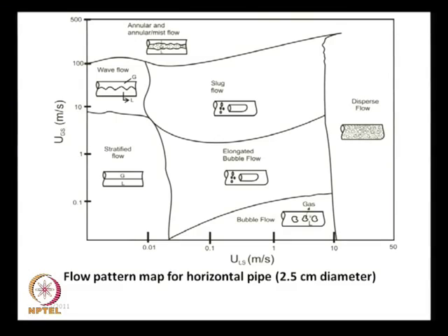For gas solid cases, we find that the Reynolds number and the Archimedes number, I believe you know about these numbers, are much more important. Usually, the maps for gas solid cases are in terms of CD versus Re, or maybe Archimedes number versus Re, and so on and so forth. These things I believe you have done a little in your fluid flow classes, in your undergraduate classes, is it not? Some portion probably.